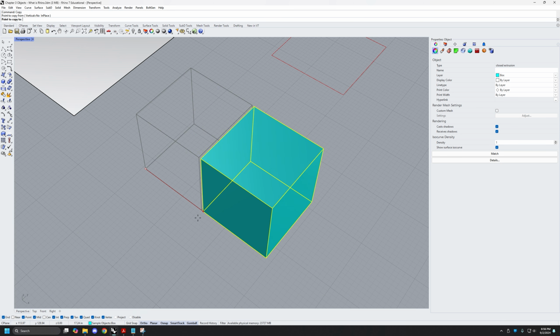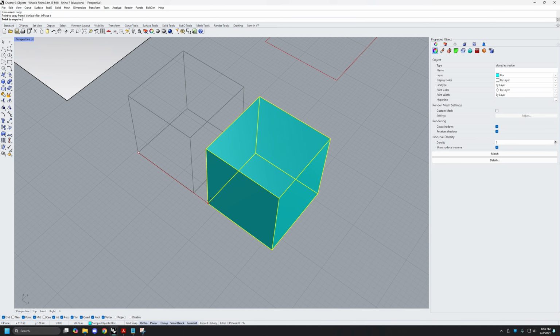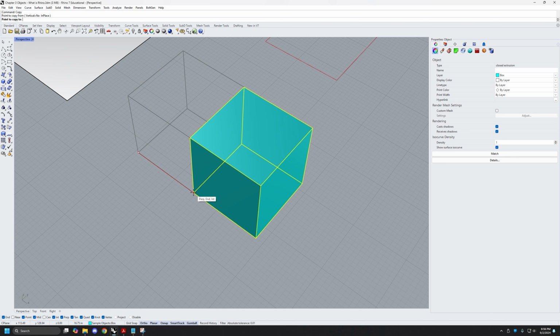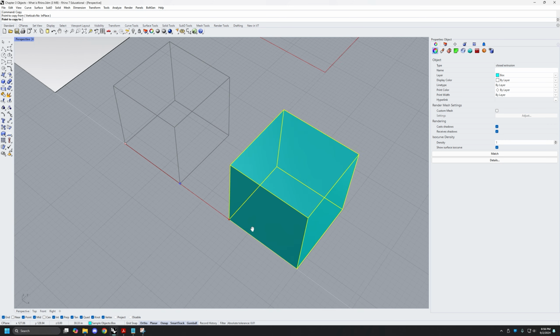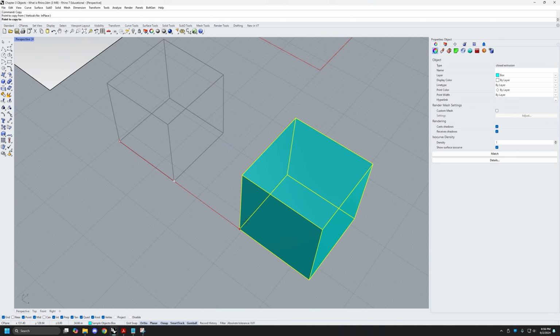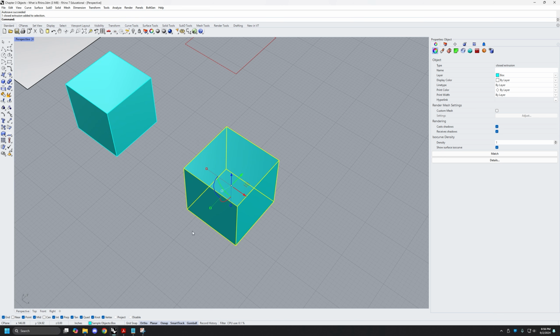And then we'll just use this tab constraint in the same way. So I'm going to hover over, and in this case, I'm not totally getting that gray Smart Track node, but I can add a custom one by pressing the Control or Command key, and there I've got one. So now I'm referencing this line here. I probably wasn't getting it because it's already on an orthogonal constraint. So, but yeah, so that's another way you can get that, and you can press tab if you really wanted to. Maybe instead you wanted to snap and copy it at a diagonal, right?